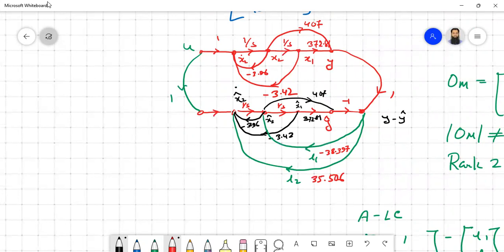As you can see, even with a second order system, the calculation is more complicated than it was in the observer canonical form. So you can easily imagine what will be the scenario if the order is 3 or more. So that is why this method is not preferred for higher order systems. Rather, convert the system into the observer canonical form, and then based on the design in the observer canonical form, get the gains L. Those L's are then transformed back to the original form.